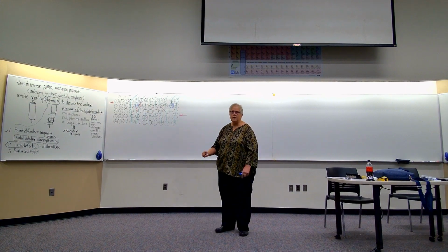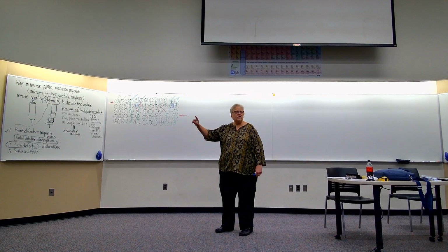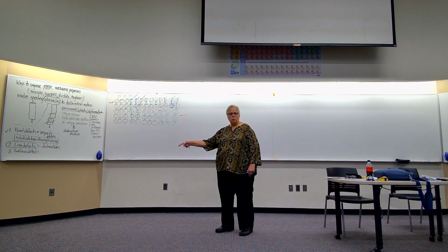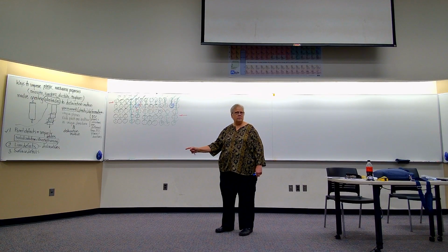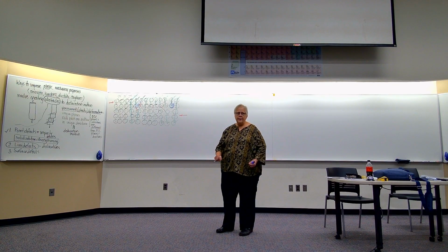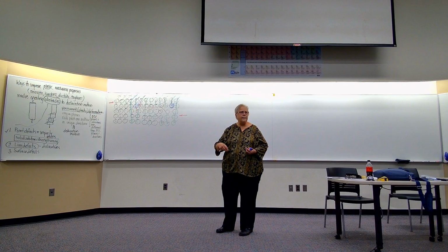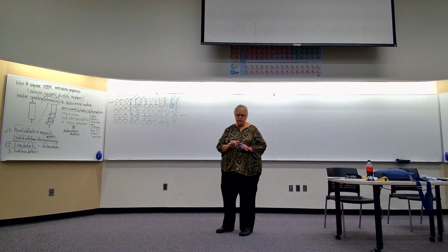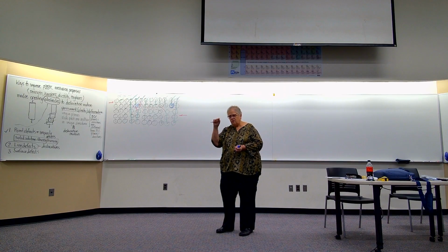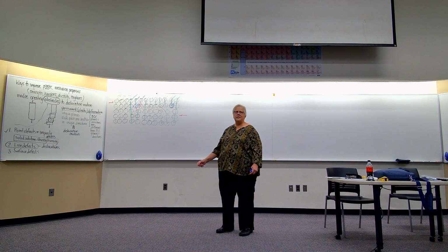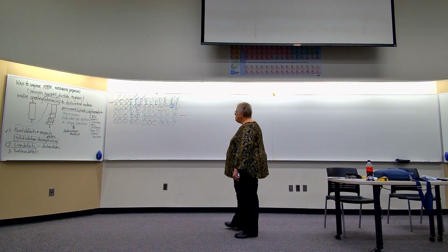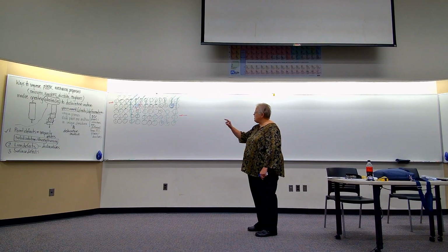So what's causing the increased strength is deformation. By deforming, the metal is getting stronger. And the classic example is if you try and bend a paperclip one way and then try and bend it back to the way it was before. The place where it's bent is now stronger than just above and just below it, and so when you try and bend it back, that place won't bend, but something just above or below will, and you'll get this sort of, I can't think of the word, but you know what I mean.